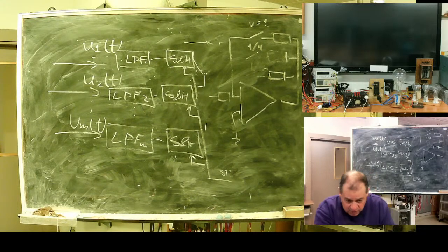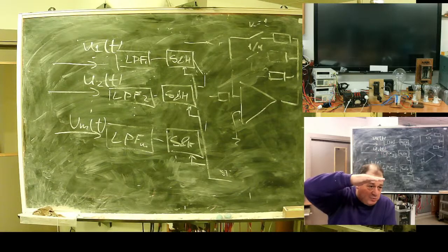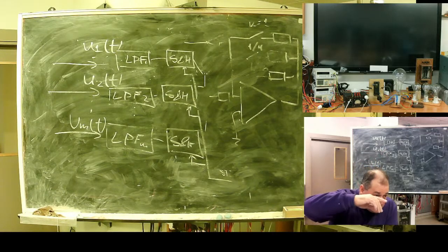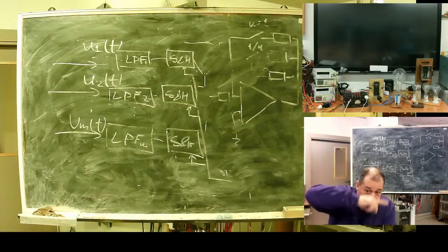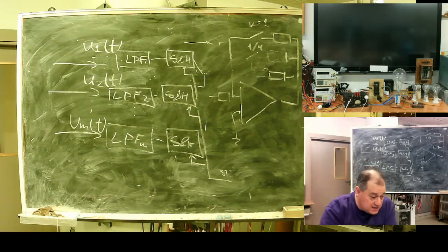Really, one moment no one thinks about. When you change gain of PGA, the same when you switch multiplexer. It's a small transient. It can have character of decaying oscillation. This oscillation may infiltrate in your good signal.